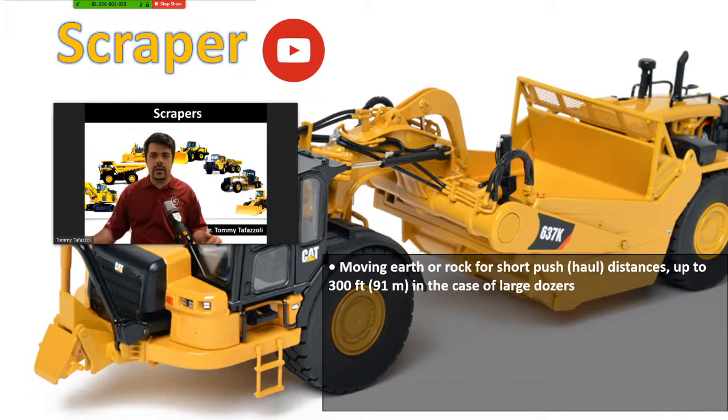The main application of scrapers is moving earth or rock for short distances, not for very long distances. Obviously, trucks would be more appropriate because they are lighter and faster, but what makes scrapers special is that they don't need another loader to put the earth on them.